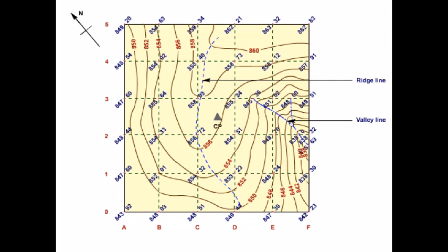So this line, like we discussed before, represents a valley line. So you have these distinct inverted V shapes, and over here, this represents a ridge line, because as you can see the elevation keeps on decreasing on successive contours, and every contour has a distinct shape that has this U shape at the center, and they coincide basically.